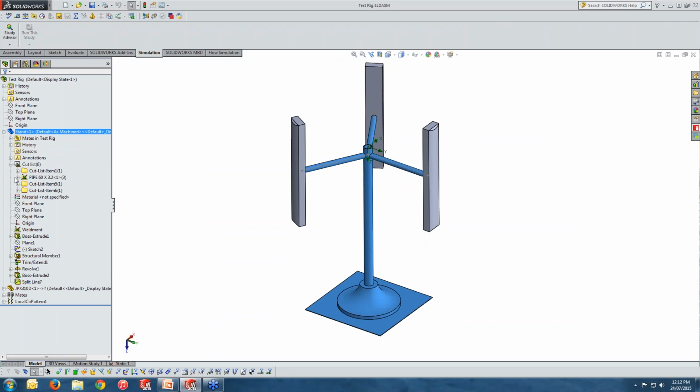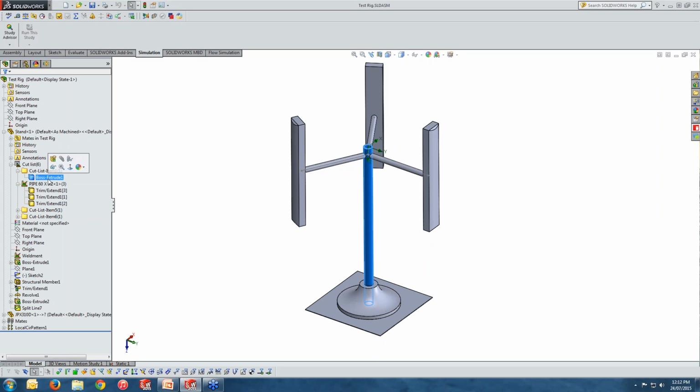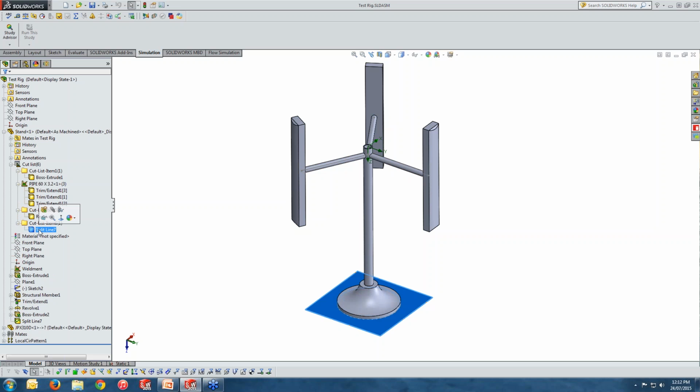We have some beam elements, weld profiles, these three objects, and also we have some solid objects like this one, and I did it on purpose. Although it is a beam, I haven't created it using our weldment profile, to show you how you can assign a beam even to a solid structure. And also we do have more, as this is the solid revolve part, and we do have this shell.